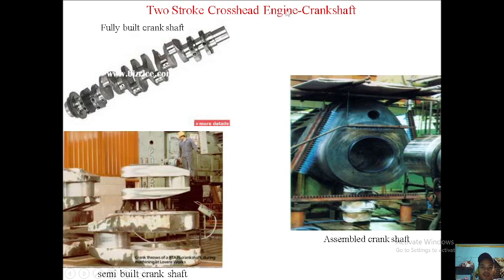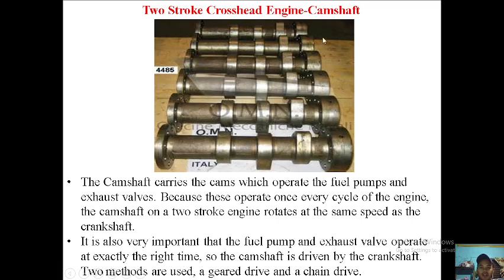So there are different builds of crankshaft. We have fully built crankshaft, we have semi-built crankshaft, and we have assembled crankshaft. Usually we have fully built crankshaft for the small ones, and you can do assembled or semi-built for big ones.